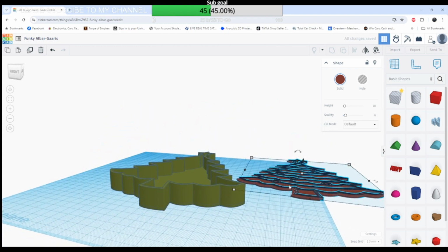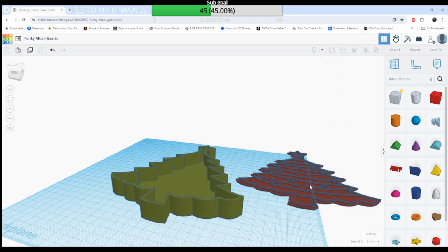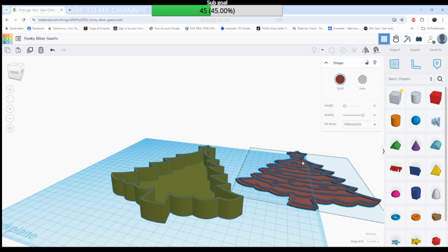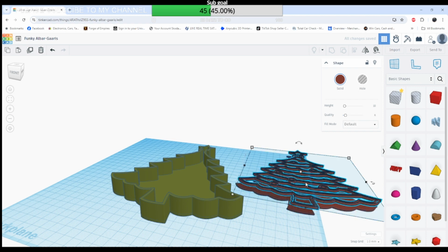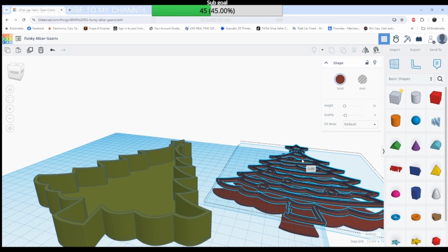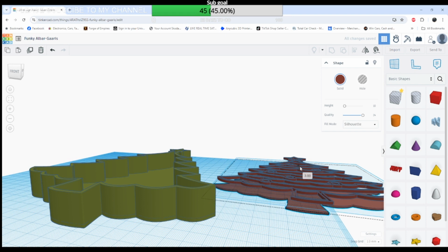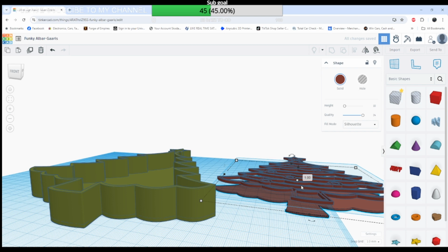But if I put those two together, it'll be merging into the bottom silhouette. So we need to raise the top one slightly. That's the bottom one. We need to raise. Let me grab that one. It's hard to see the black. There it is there. We go 3mm off the base. And this one we put on the base. Like so.